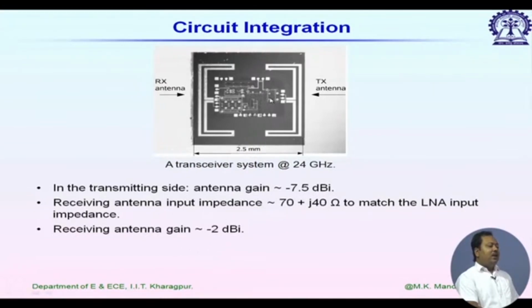This is due to the coupling between the circuit part and the antenna radiator. Here they are not using any guard ring or any precaution, they are just placing the antenna radiator away from the circuit part. And now we put maximum importance on the receiving antenna, since the received power is very small and we have to detect it.